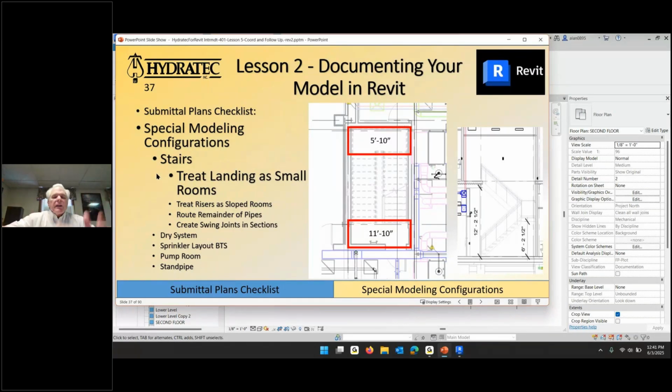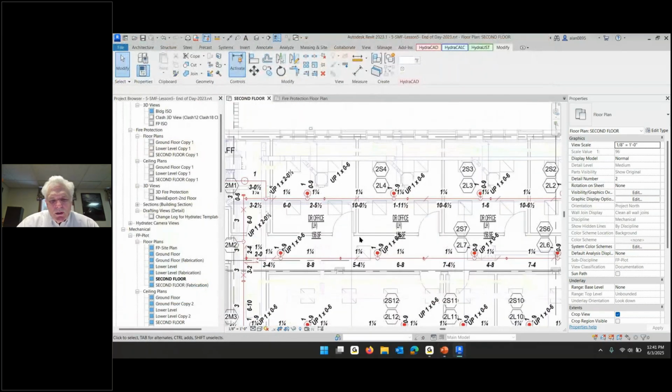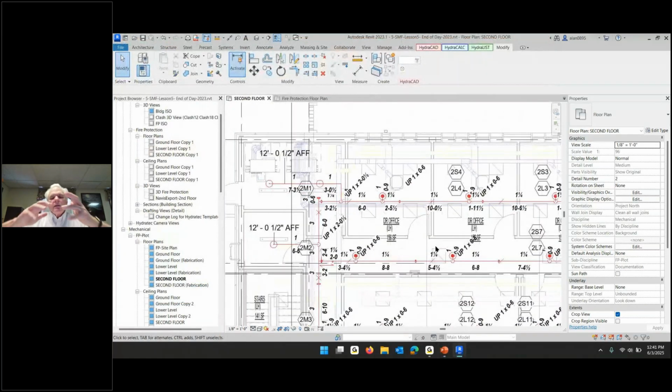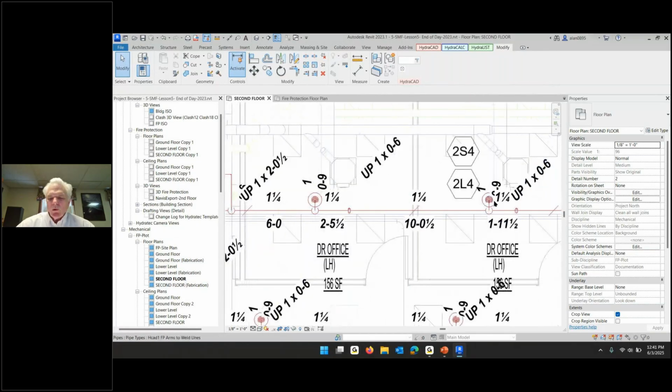However, not on this list, but on my handwritten list, a question came up about dimensions, and dimensions are really cool in Revit, but I want to explain some of them. I want to put a dimension from the inside of the wall to this branch line, to the inside of this wall, to the other inside of this wall, to this arm over, and like that.